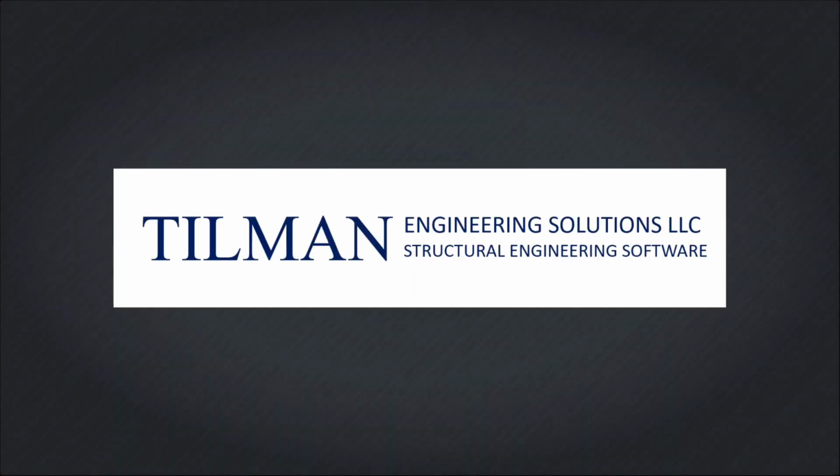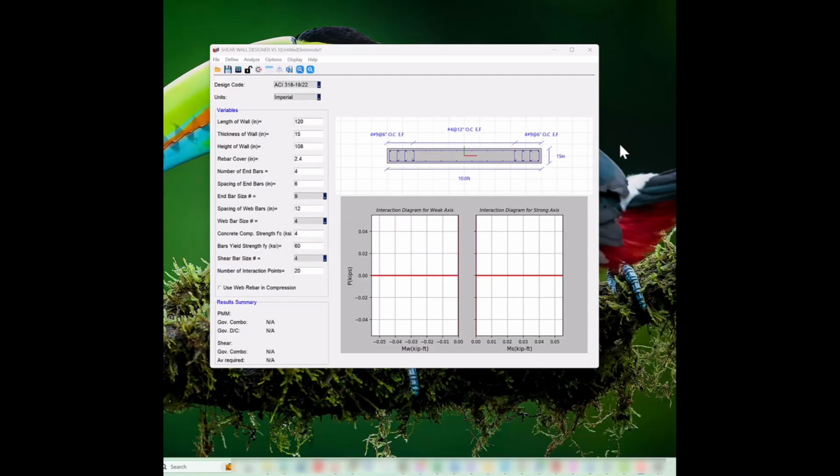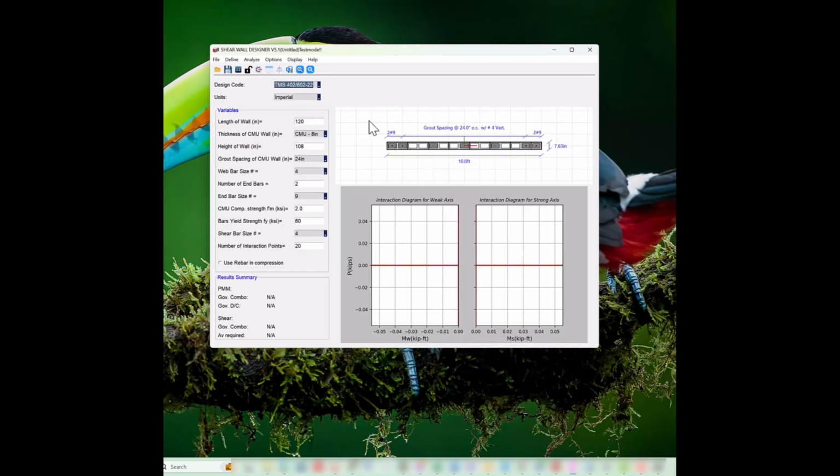Welcome to this tutorial about a major enhancement introduced in Shear Wall Designer version 5. In this case, the option to design masonry shear walls as per the 2022 TMS 602 Masonry Code. This option is available under Design Code. Notice how when selected, the sketch of the wall automatically changes to masonry.